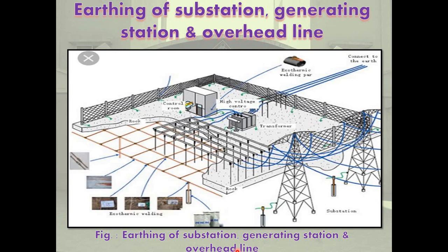The joints are welded. Risers are vertical rods welded to the mesh. Several vertical earthing spikes, like electrodes, are driven in the area, and these are connected to the earthing mesh by means of welded steel rods. Various points to be earthed are connected to the earthing mesh by means of conductors.